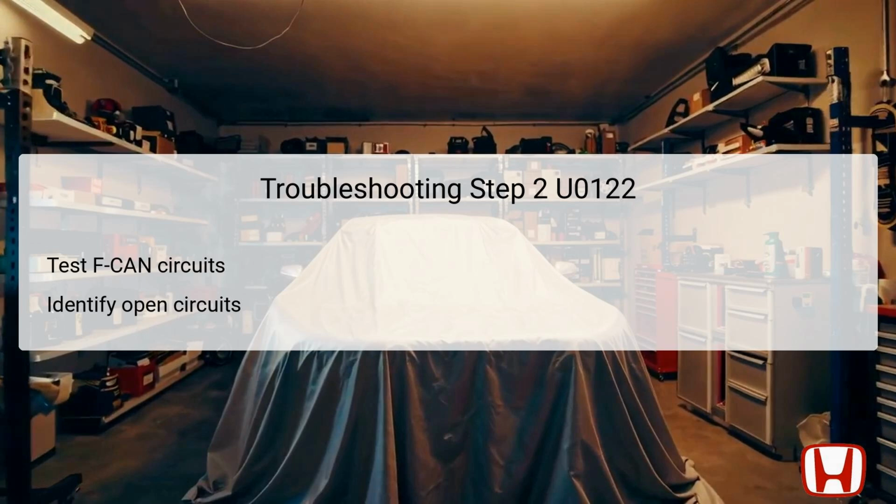accordingly. Understanding that either the FCAN_H or FCAN_L line being open can inhibit communication provides specific guidance on where to focus repair efforts. This step is critical for isolating the root cause of the problem.